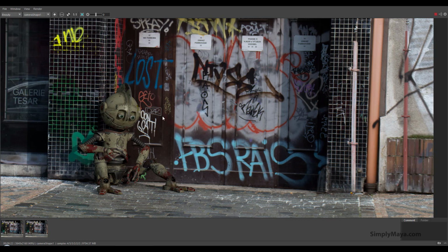For those of you that want to be able to individually color grade the diffuse contribution, you want to be able to individually color grade the background from the robot itself, because the blackest black parts of this robot do not actually match the blackest parts of this image. So you can get a better shot by splitting it up into its component parts and rendering it out individually.